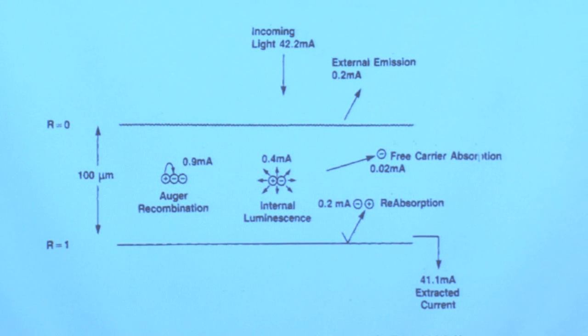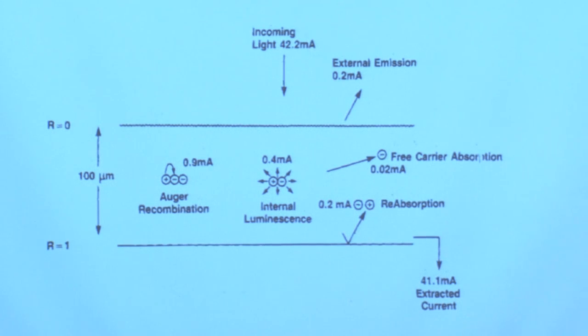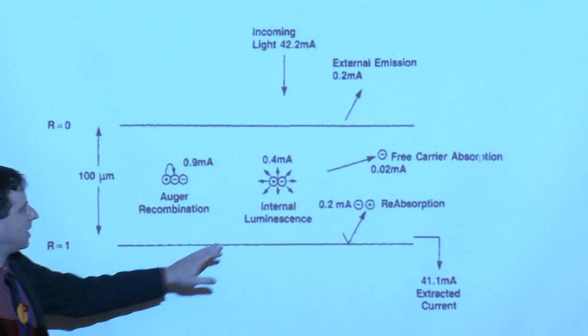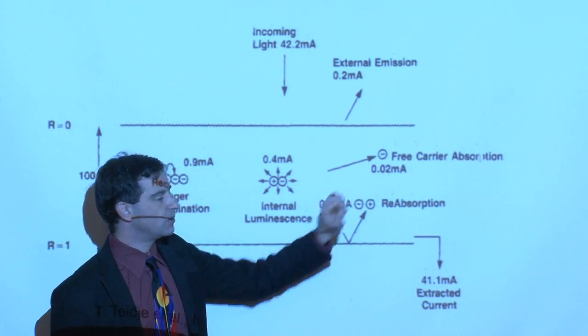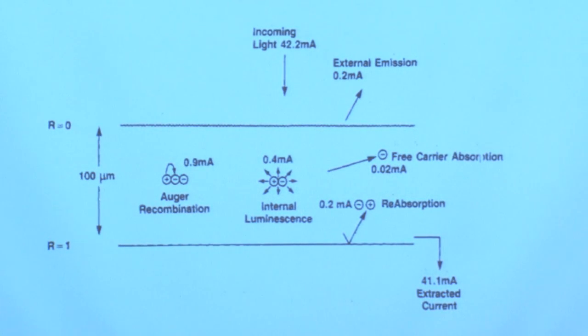It emits a photon inside of your solar cell device, and that photon bounces around a few more times until it's reabsorbed, generating another electron hole pair. And that is essentially the major boost in some of these ultra-thin, high-performance solar cell materials, such as the Alta Devices record efficiency 28% gallium arsenide cell, is the ability to do this photon recycling.